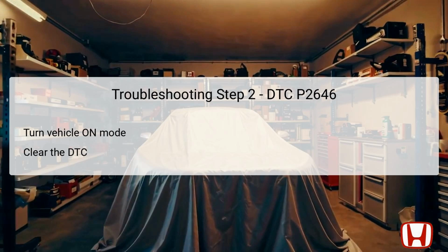After ensuring the vehicle is in the correct mode, the next task is to clear any stored diagnostic trouble codes, including DTC P2646. Clearing the codes allows for fresh data to be collected during subsequent testing phases without historical errors clouding results. Following this step, it's crucial to perform a VTEC test via the HDS's inspection menu. The results of this test will either confirm intermittent failures or point to a possible duplication of the error, guiding the technician to the next necessary action.